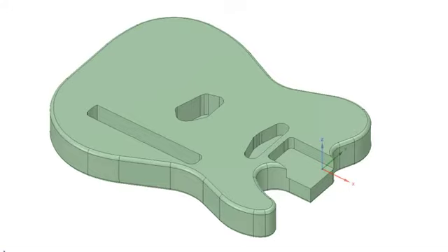We have the ability to capture different features and different types of geometries in different ways. So where you've got true geometric shapes, those can be captured with the hard probe at a much higher accuracy than the more freeform surfaces that are best captured with the laser line probe.